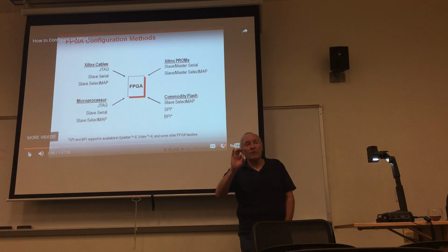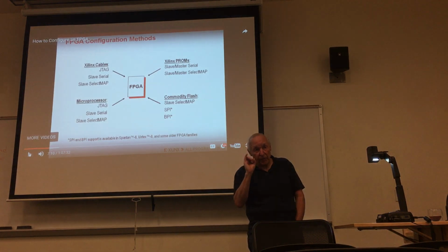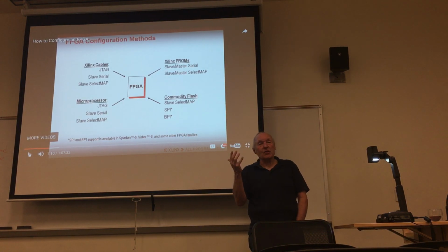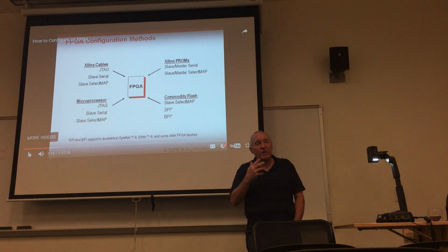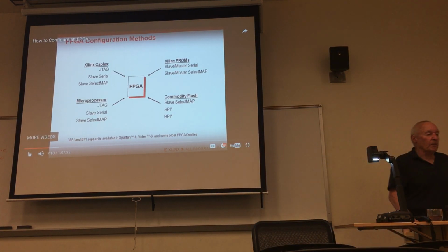But the non-volatile memory is external because, as he said before, the FPGA SRAM cells are smaller than if you made a flash. And so I can put more stuff in the package if I go with SRAM. So the non-volatile memory will be on the printed circuit board, but external to the FPGA.